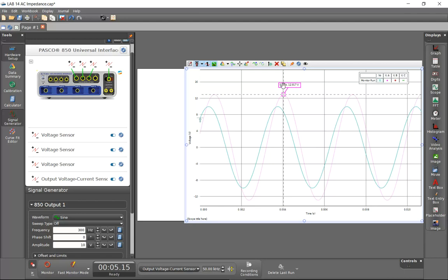That's a larger voltage across the capacitor than we're putting into the circuit. How is that possible? It stores some voltage. It's storing energy, and it's got a positive voltage when the inductor has a negative voltage. And so the sum of the positive capacitor voltage and the negative inductor voltage is going to come out less than the voltage we're putting in. So you can actually get a larger voltage than you put in because it's not at the same time.